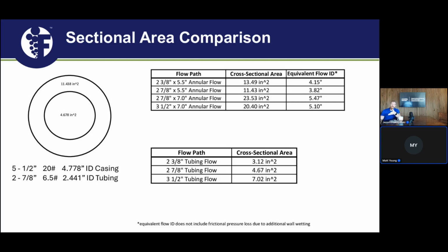The con to that is it's hard to get big tubing in a well that has 5.5-inch casing. Your best case, you're going to be able to put 2 7/8. If you really convince your completion or your workover foreman that you can put 3.5-inch tubing in your 5.5-inch well and be able to fish it out later on in life, maybe you can get 3.5. But usually with 5.5-inch casing, you're going to be confined to 2 7/8 tubing or smaller. So that's kind of the con.